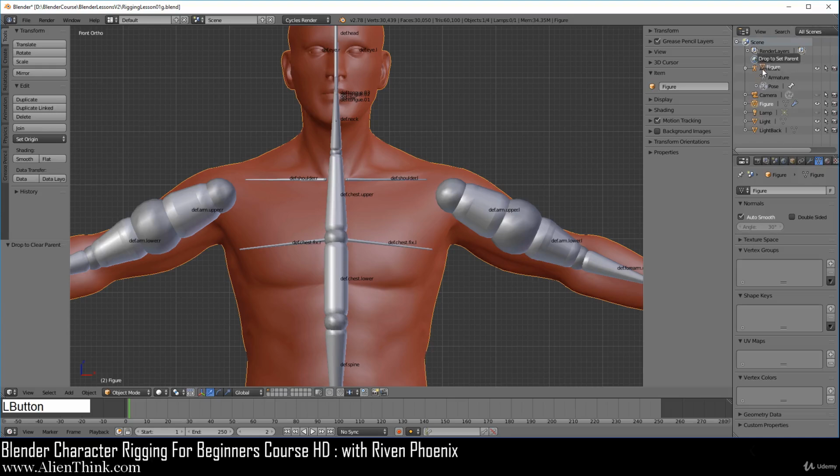And when you drag it onto the armature, you'll see that over here, all it's really asking you is, if you set up the bone envelopes for your character correctly, it's talking about the white space. Do you want to use that white space to create the vertex groups and assign the vertices to those vertex groups based on that white space?